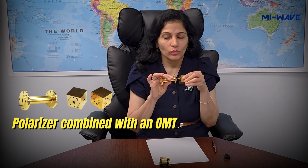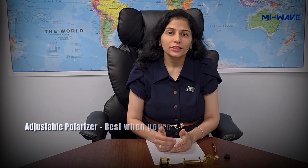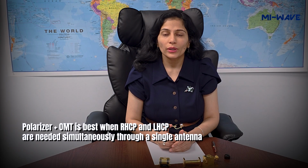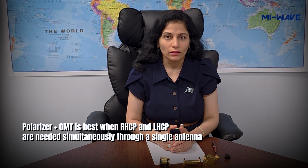And if your application needs RHCP and LHCP simultaneously, such as in satellite ground stations or dual polarization communication systems, then the ideal solution is a polarizer combined with an OMT. So to summarize, fixed polarizer, best when polarization is required permanently. Adjustable polarizer, best when you need to switch between linear, RHCP and LHCP. And finally, polarizer plus OMT is the best choice when RHCP and LHCP are needed simultaneously through a single antenna.